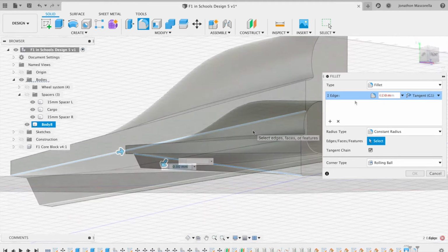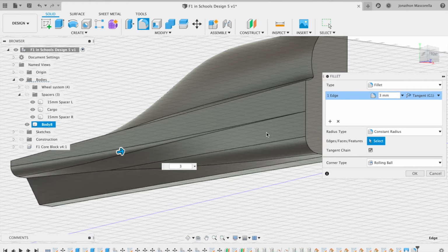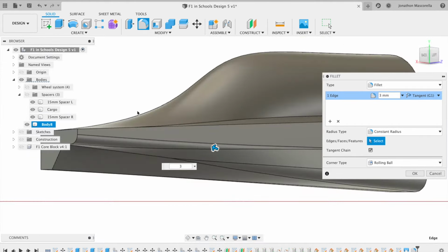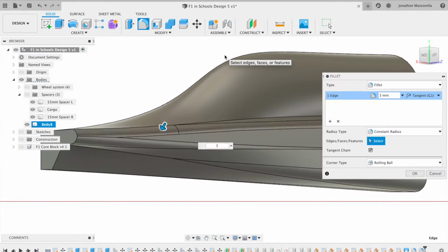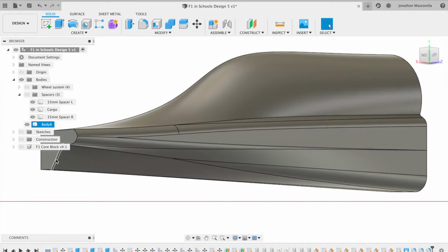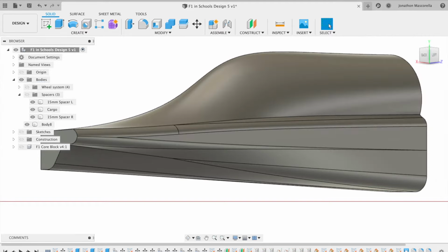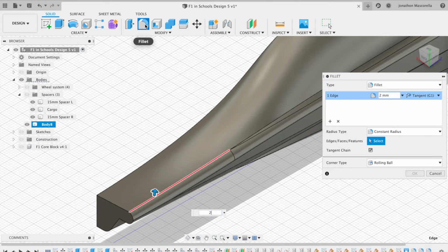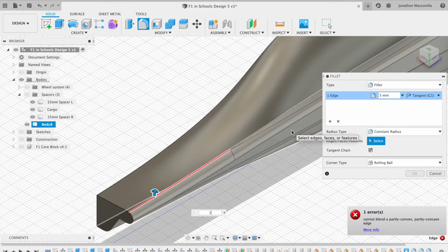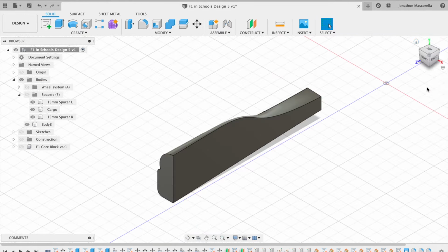So you do get some modifications between what you can drill on the CNC and what this creates, but there's not a lot of scope to really do things out of the ordinary. You need to keep pretty close to whatever you've drawn. That's why here I'm rounding off the edges, to try to minimize any sharp angles that I know the CNC router can't get into when it cuts this thing side to side. And of course, even to that degree, we're relatively limited in the ways that you can cut this out.